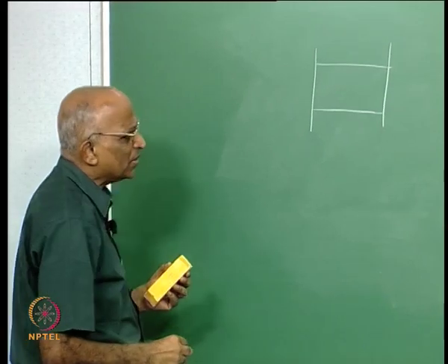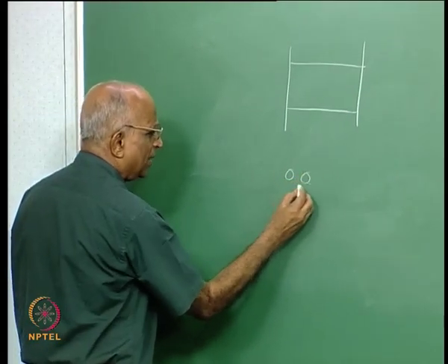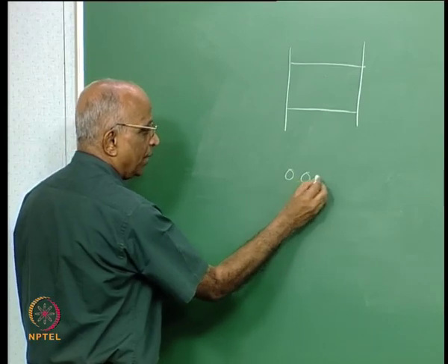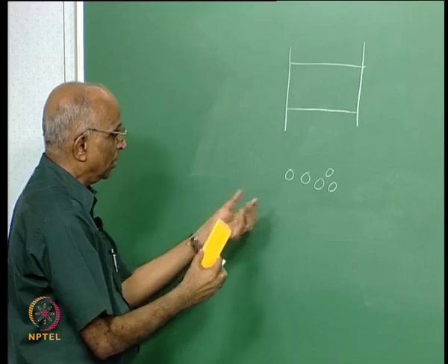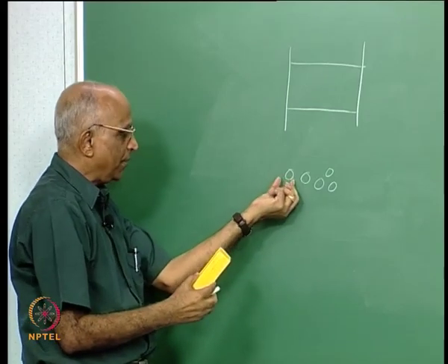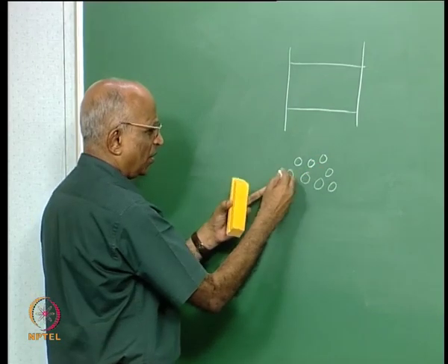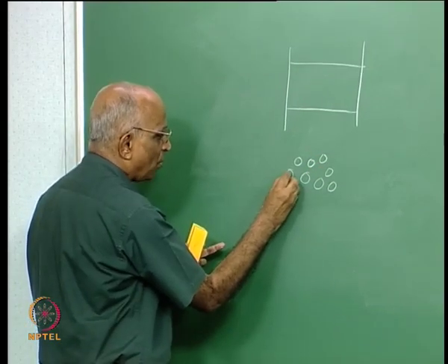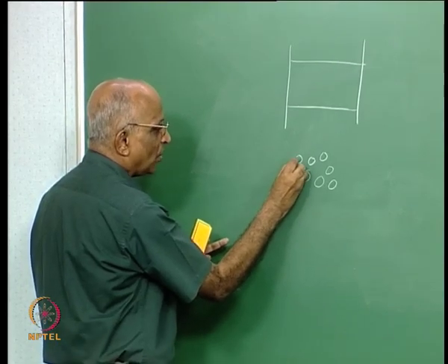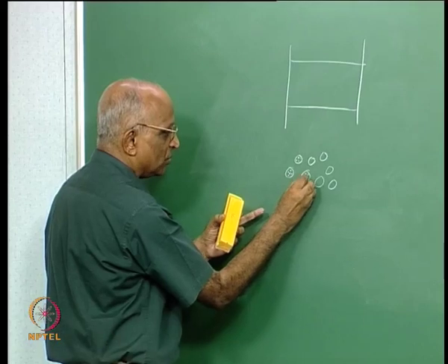All that I need to do is put catalyst over here. And how do we put this catalyst, like iridium? I have balls; I need iridium to be coated, and I take maybe alumina, which is something like a porous refractory. I make balls of alumina, maybe 1 mm or 2, 3 mm in diameter, spherical ones, and into this I coat iridium on it.